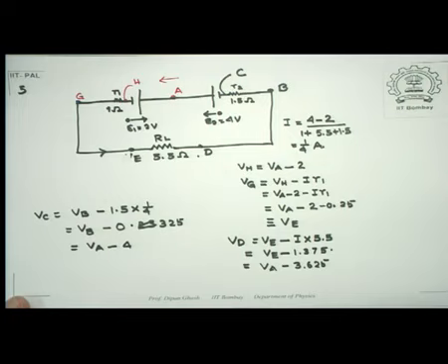So this essentially tells you how the potential drops are to be calculated. Now here I assumed a priori that the current is in that direction. You don't really need to know the direction of current. Suppose you did not and you assume the opposite. So when you go opposite to the direction of current, then of course as you go through a resistance, we have seen that the potential will rise.